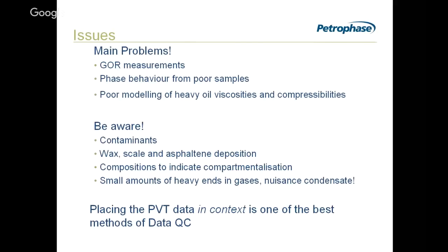The last point here, placing the PVT in context. That's actually one of the best methods of data QC and what we should really be doing. It's like saying, well, we've done our test, here's our PVT sample, that's it. Well, it might be it for that moment. What about the rest of the test? Does that sample fit in with the samples that were previous to that? For the different flow periods, can we model those with the same composition? Does it work? So rather than looking at the data as though it was a snapshot from a camera, view the data more as though the whole well test was a movie, and we want to understand the whole story, because that's much more powerful, that's much more useful information.